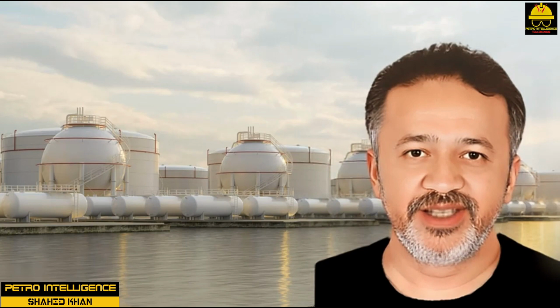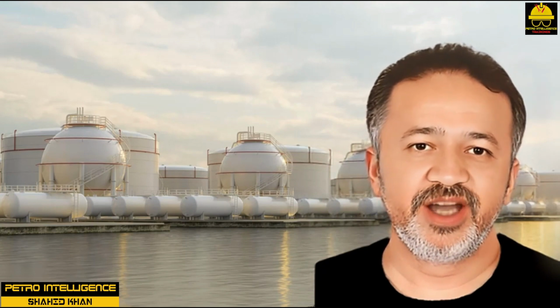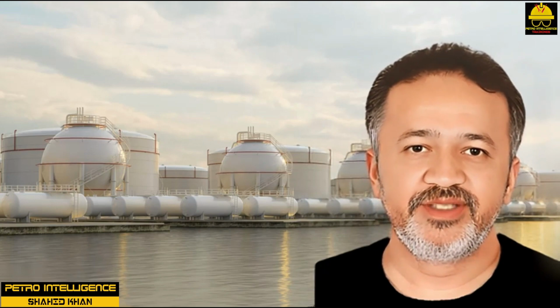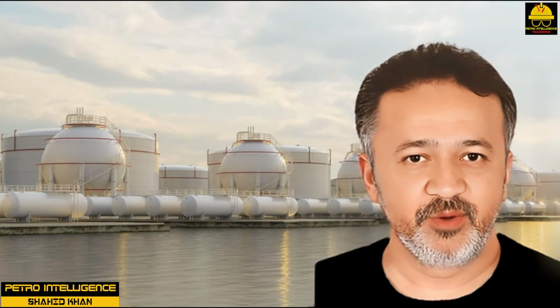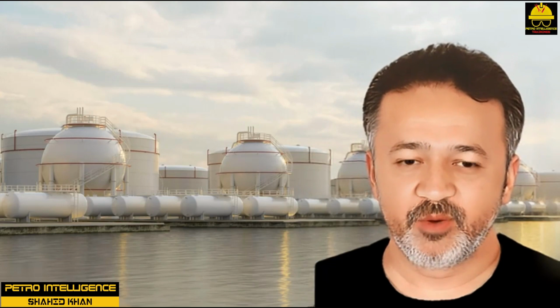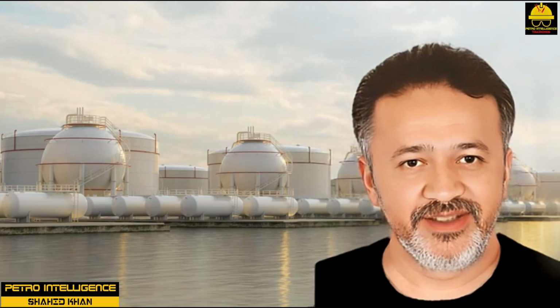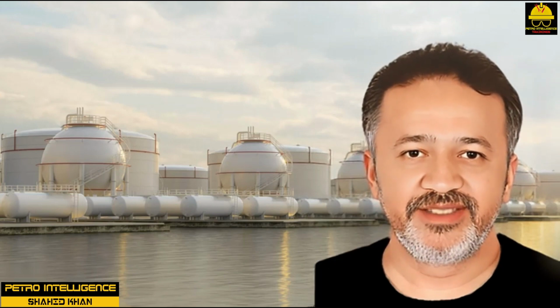Bonding and grounding tanks, pumps, and piping. A static electric spark can be an ignition source and cause fire or explosion. This takes place when an electric spark discharges across a certain distance between a charged body and an uncharged body. Flammable liquid containers can build up static charges as the material is pumped in. Fluid movement of any type can produce a similar effect.